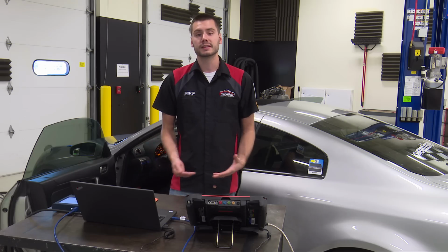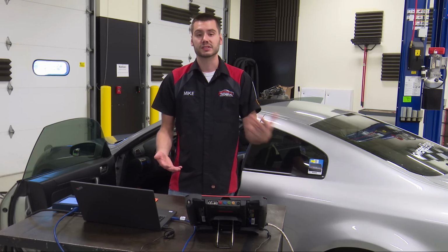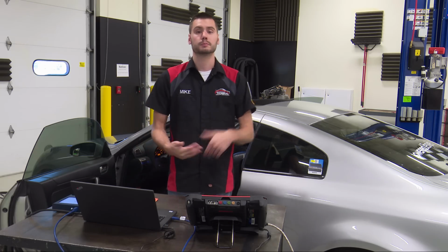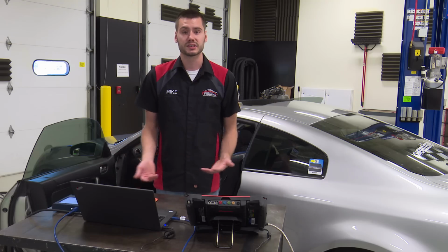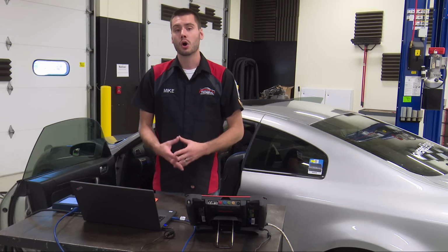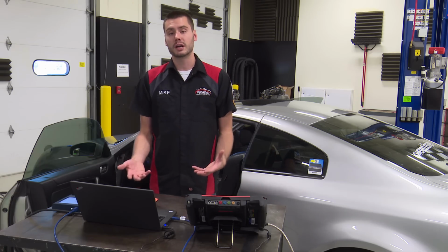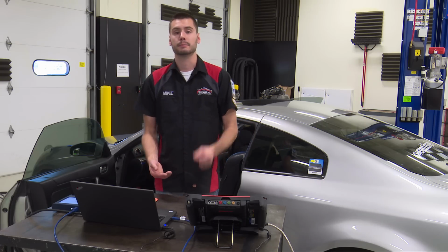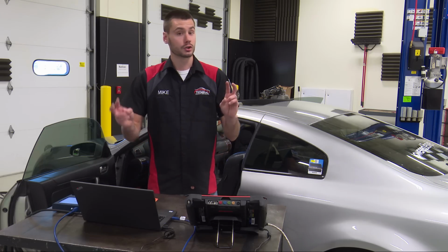How often do we see cause and effect failures, right? The cause for the failure was something and it affected something else. Spark plugs taking out ignition coils, blower motors themselves taking out blower motor resistors. We see this kind of stuff all the time. Is it possible that our window motor took out our original switch and then with a new motor, a new switch, everybody's happy again? But what if our new motor isn't a good motor?